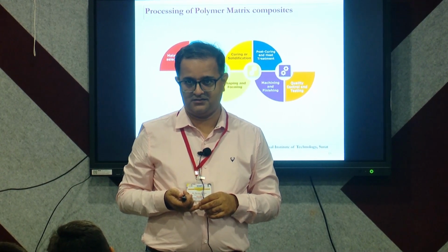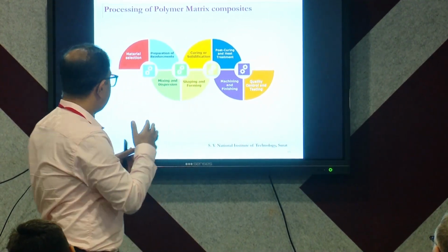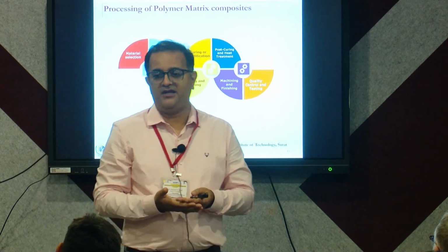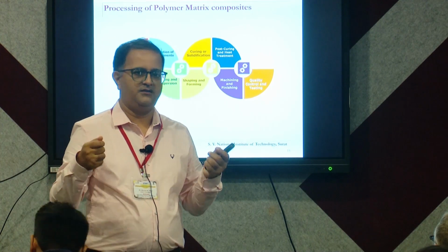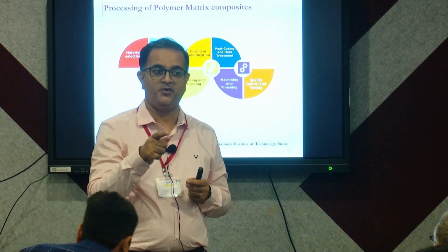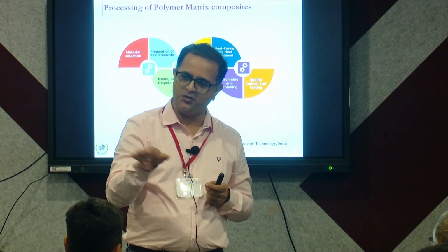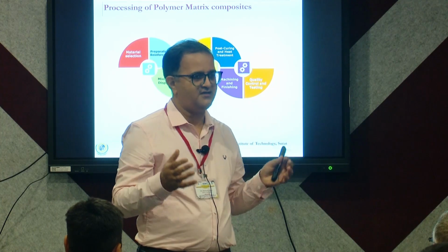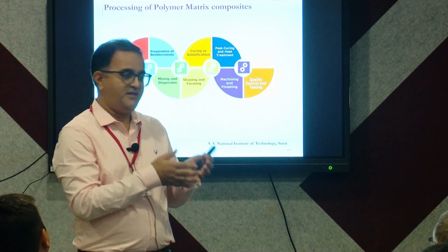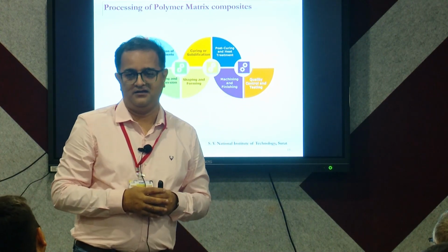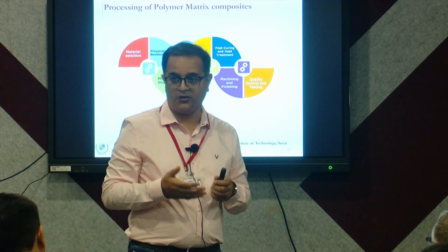No, that is a matrix. I am talking about matrix at this point of time. So once you have this fabric, or once you have the short fibers, or maybe a combination of fibers, whatever it be, you will need to allow them to cure. It depends upon how you have infused them. Have you put them under pressure? Have you just used a brush to place these resins? All of these things will have their effect on the curing part. So depending on the process, the curing and solidification will become a specific task for caution, for study.